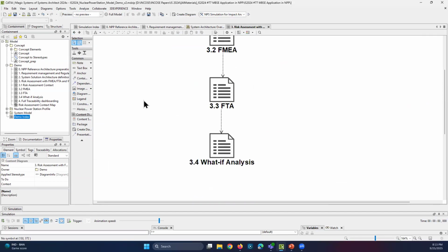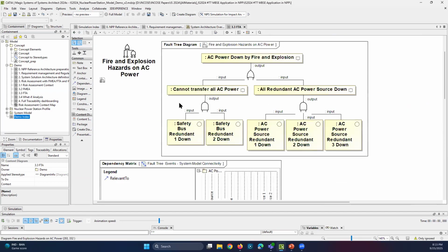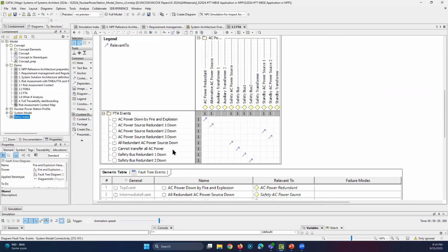Then, of course, we can continue to do the FTA to start to analyze, because the FMEA is a qualitative method, right? So it really relies on the engineer's experience, where the failure may happen, to what component or functions, and how is the detectability. But FTA complements the FMEA by giving us the probability and the quantitative method. So we start from the failure at the top events and break it down into the basic events, and identify from the basic event to the actual components, right?